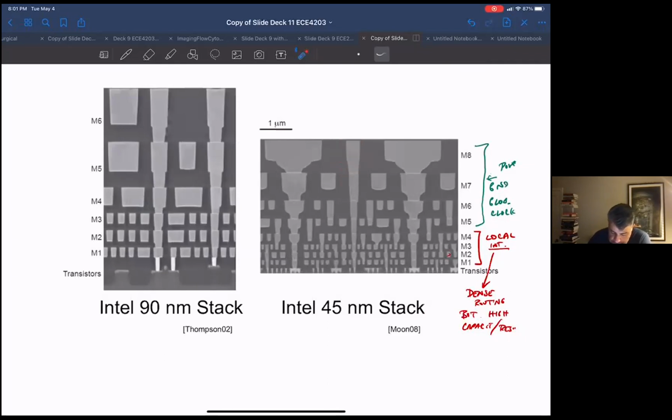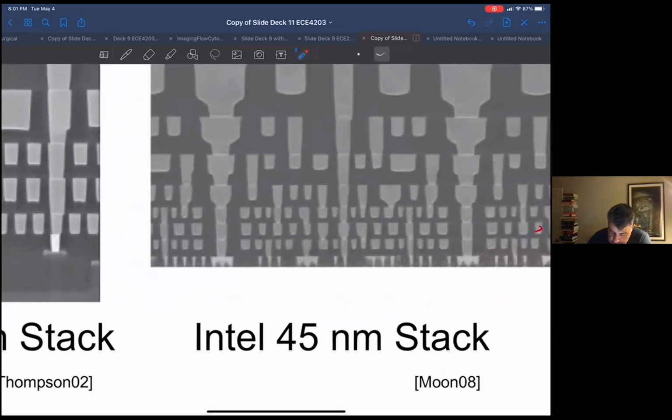Let's say, for example, this was the dielectric thickness. If you look at this height, it's as much as your dielectric thickness. In fact, when you get to these two guys, this thickness that we ignored is much more than the dielectric thickness between the metal lines.